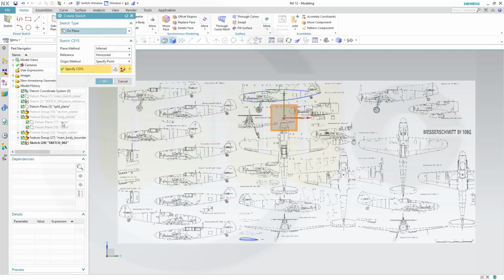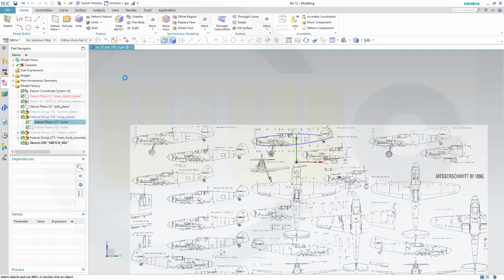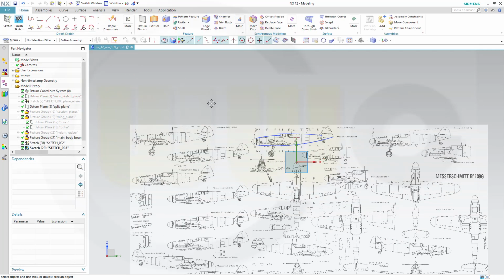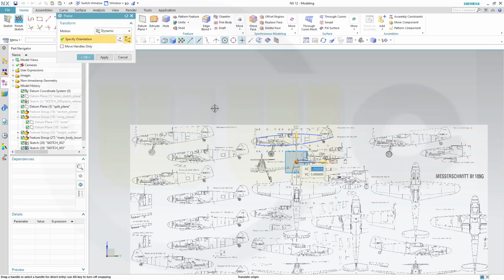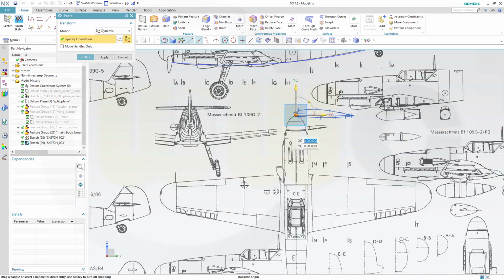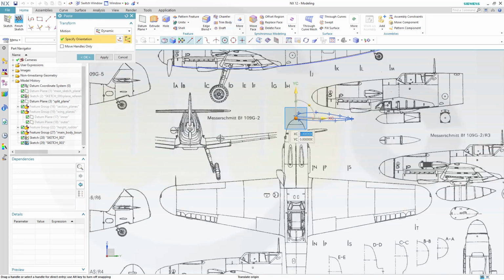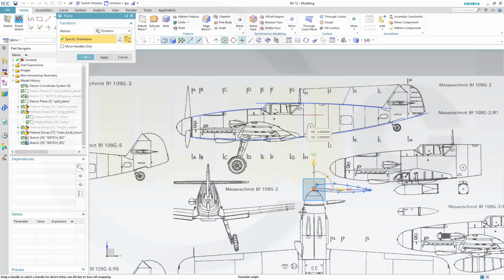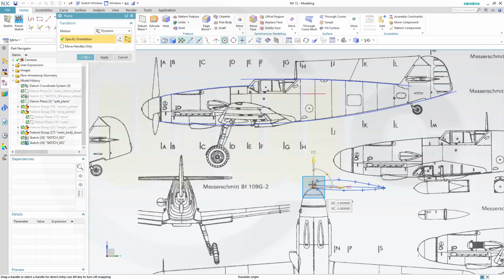Select the inner wing plane, confirm, and Control V and paste that profile. Let's see, that looks okay. And now move that profile to the position where you want it to be. Somewhere over here. You can move those wings later on anyway, so it doesn't really matter.